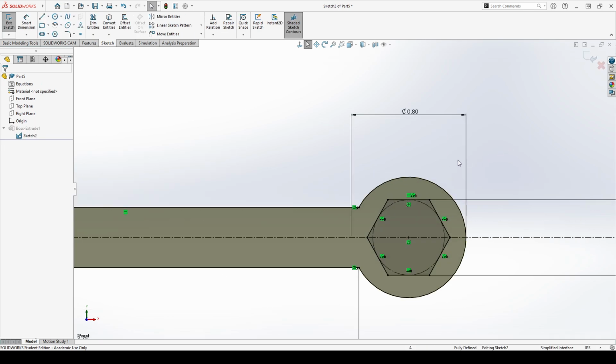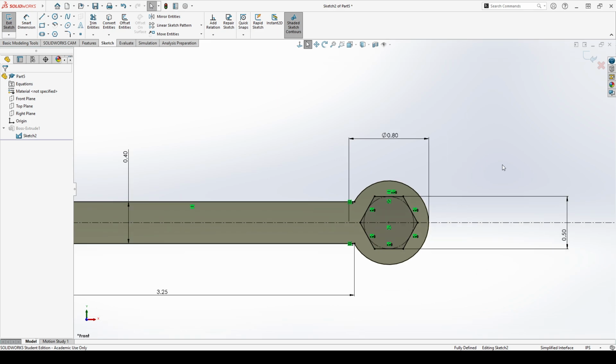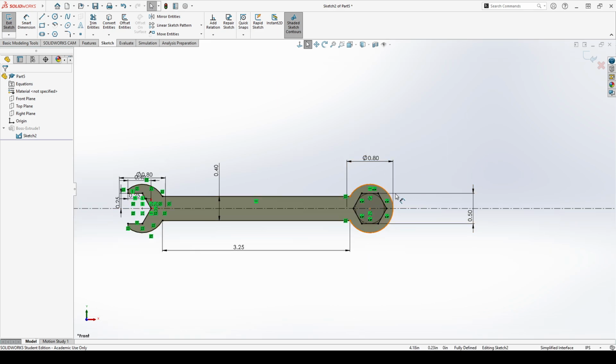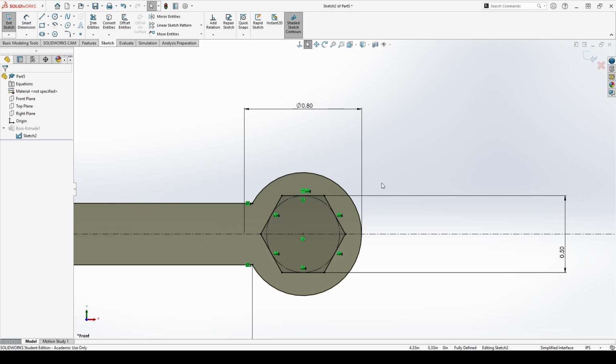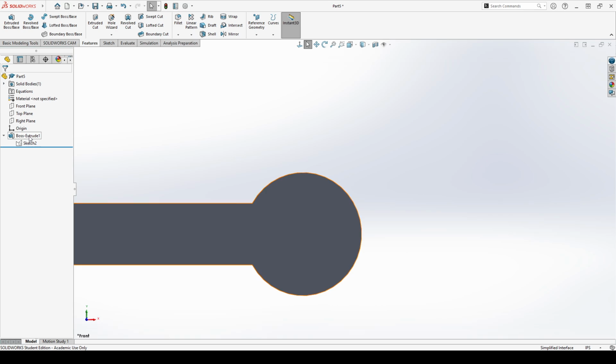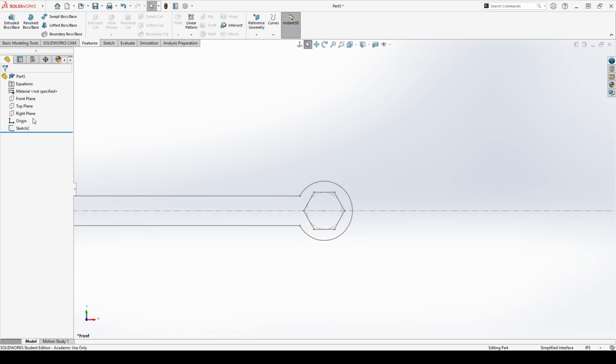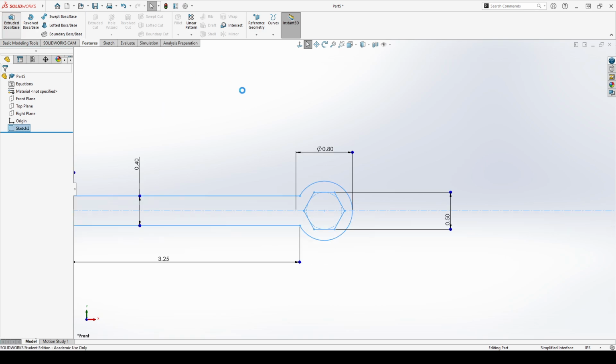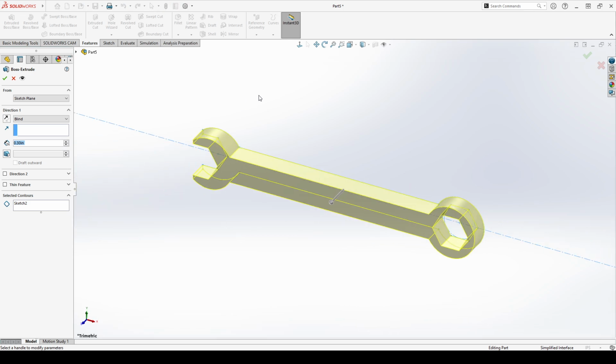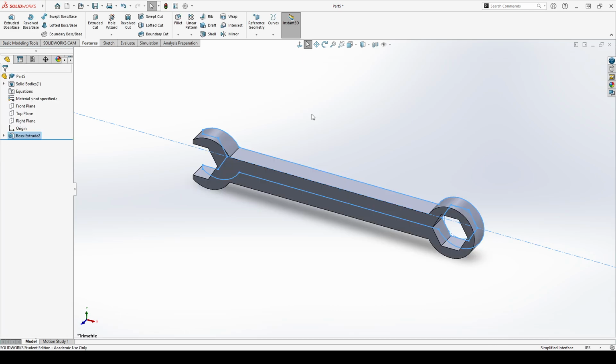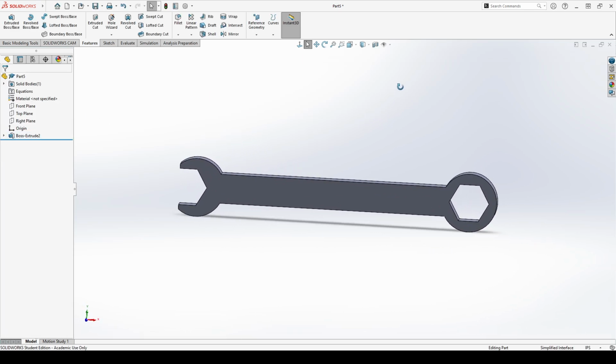What happened to our hexagon? Isn't it supposed to be hollow? Well, when selecting the sketch for this extrude, we messed up. So delete the feature, select the sketch, extrude it out, including all the individual components that we sketched, and then click OK. Or you can just physically choose it independently inside.